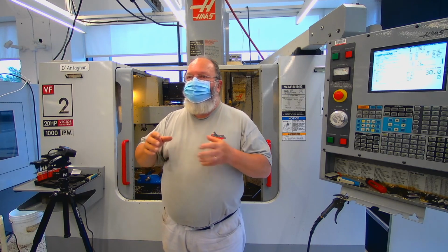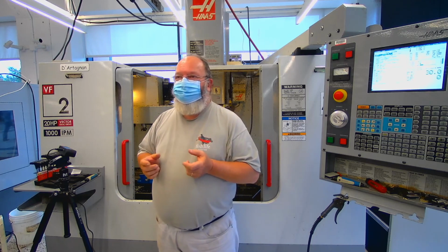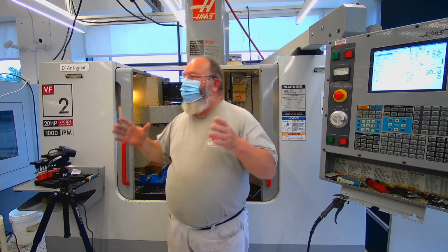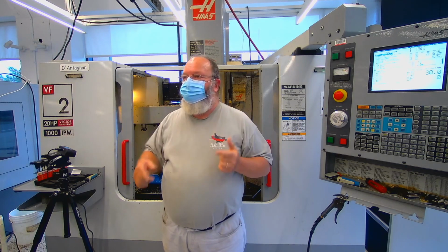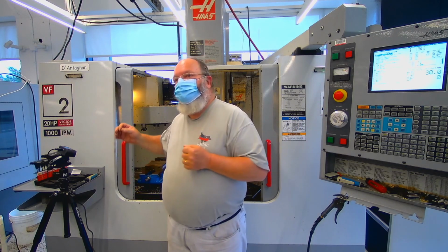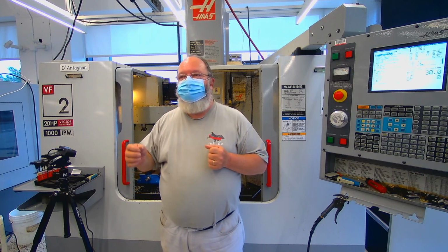It was very common way back when. You put some glass in there and you make jewelry out of it. They also do the same process in a vibratory method in a large vat. They keep rolling it through the stones. Deburring can be very expensive, depending on how labor intensive it becomes.